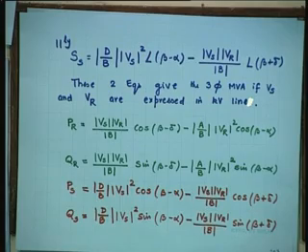So, what do we do? We separate real and reactive power. Okay, imaginary, real and reactive powers, so that we get our old friends cosine and sine back. So, PR is Vs Vr by B cosine beta minus delta minus A by B Vr square cosine beta minus alpha, and QR is Vs Vr upon B sine beta minus delta minus A by B Vr square sine beta minus alpha, similarly PS and QS.